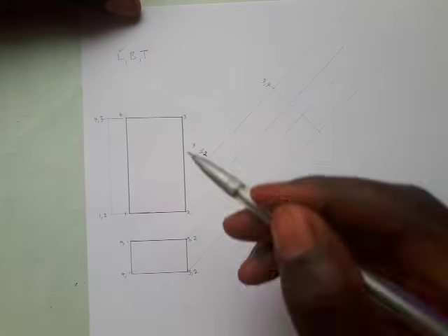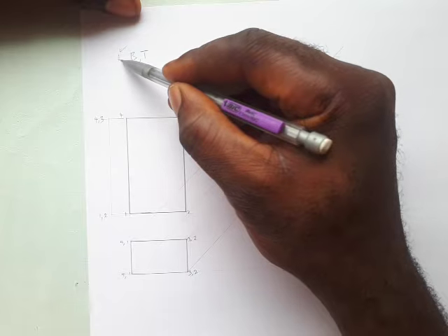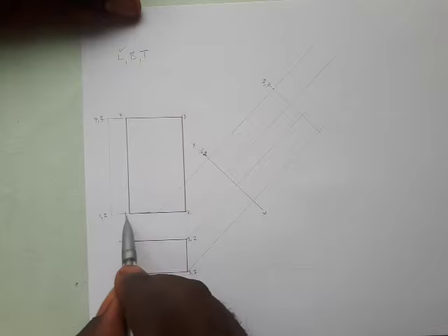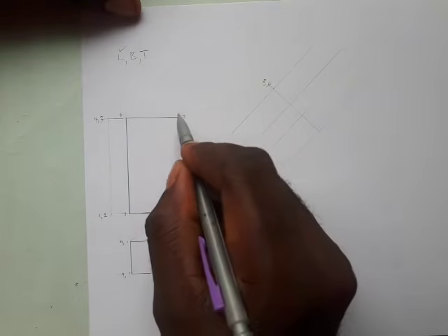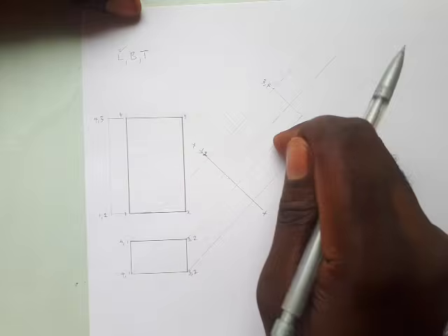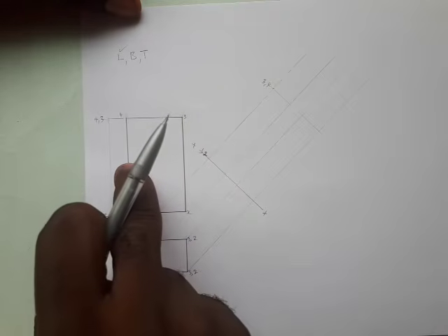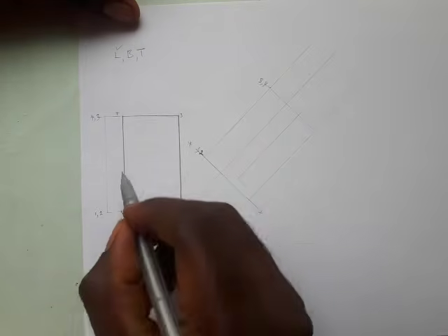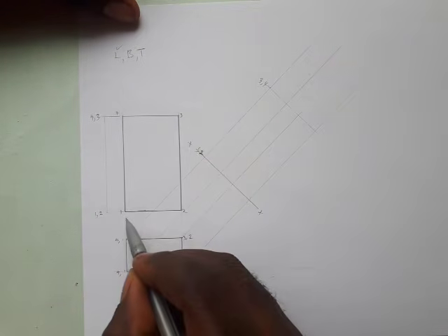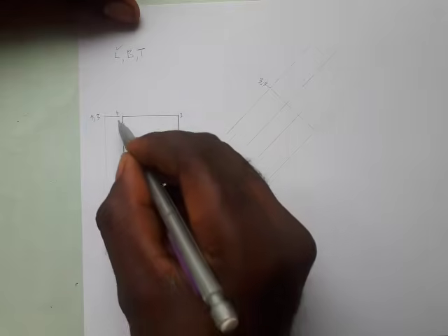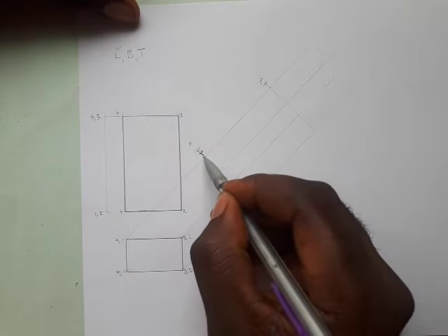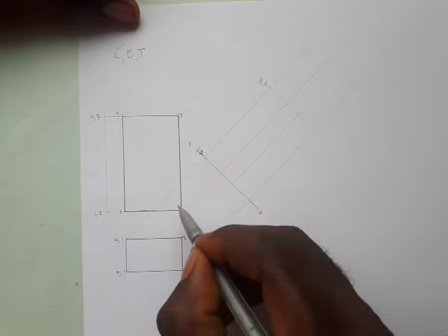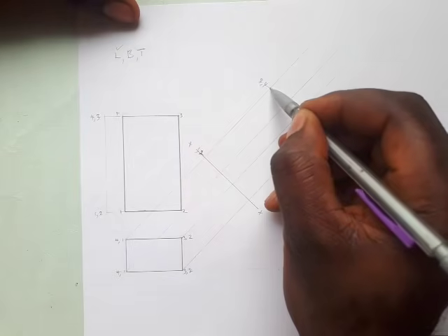So let's start with this. We are dealing with all the length, isn't it? Now the question is, where are all the lengths? We have 1 to 4 and 3 to 2. So come to this auxiliary and do the same thing you are seeing here. You have 1 joined to 4, isn't it? So where is 1? Just follow the line and move to the auxiliary. You have 1 here and you have 4 here. They joined 1 to 4, so come over here and also join 1 to 4.